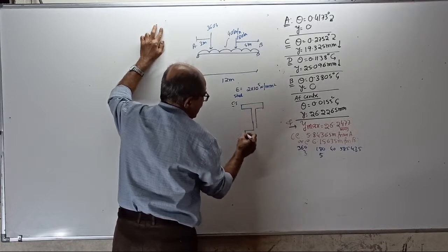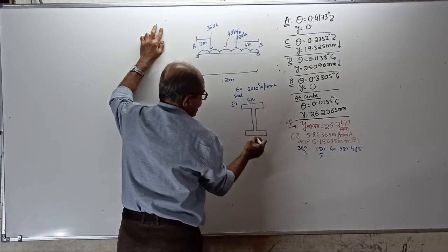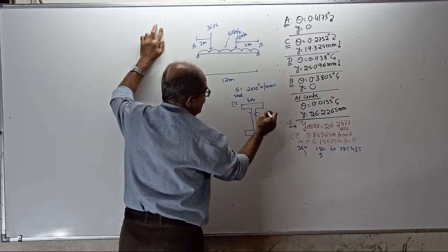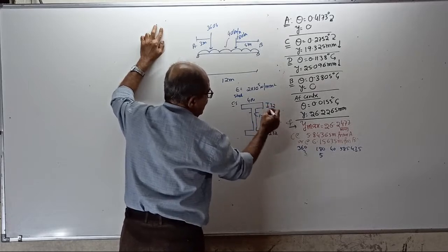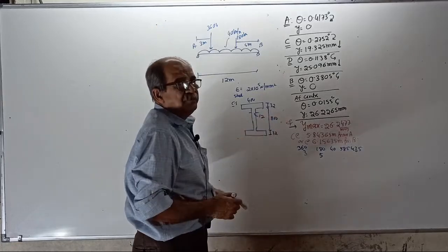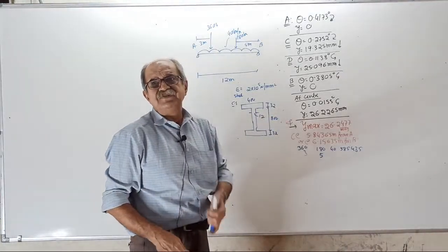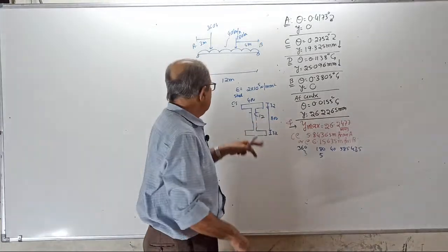If I remember correctly, I will tell you now. Flange width 400, thickness of web 12, thickness of flange 32, and depth of web 800, because I designed it. Before giving the section, I remember, because I designed it. Correct now, this is the cross section, all in millimeter.